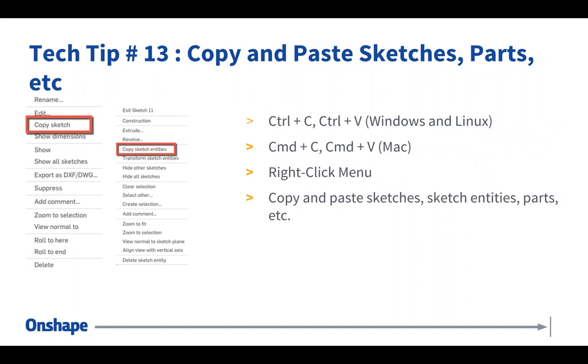Number 13, copy and paste. This is another frequently asked question. I have these sketches that I always reuse, or I have these features that I always reuse, these parts that I always reuse. Is there a way to copy and paste sketches, sketch entities, parts, and so on? And the answer is yes. If you're using Windows or Linux, you can use Control-C, Control-V. So those that are fans of keyboard shortcuts, those keyboard shortcuts are supported. So you can Control-C a sketch and Control-V a sketch or a part.